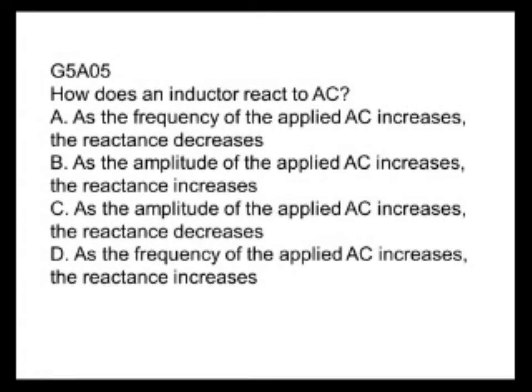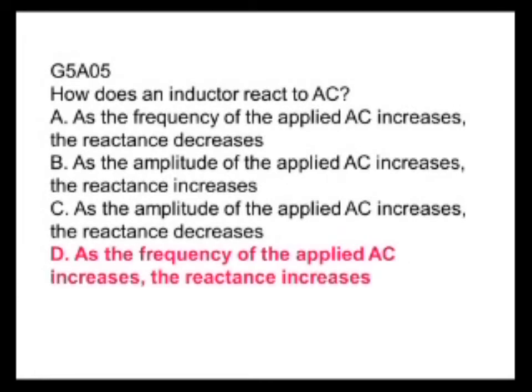How does an inductor react to AC? Okay, as the amplitude of the AC increases, the reactance increases. Did I say amplitude? Slap me, somebody. Amplitude has nothing to do with reactance. It's all based on frequency. As the frequency of the applied AC increases, the reactance increases. So in an inductor, as the frequency goes up, it's more difficult to get the current to flow.